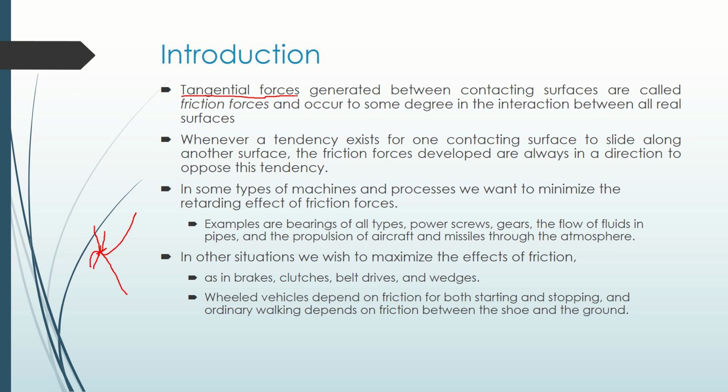One of the most common types of failure most motorcyclists see is the failure of their clutch wire or brake wire. Why? Because the outer layer of the cover is basically made of steel. It has internal steel wiring, and the internal cable is also steel. The two surfaces come in contact with friction, and they rub across each other.